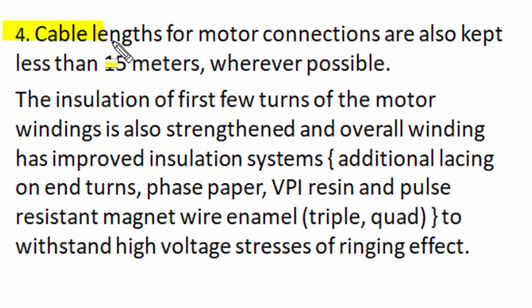If a longer length of cable is used to connect the VFD and motor terminals, especially when motors are mounted at a certain height on process equipment, then the longer cable creates voltage transients that may damage the insulation of the connected motor. So we should limit the length of cable connections from VFD to motor to less than 15 meters wherever possible, as voltage transients may get produced by VFD connections.